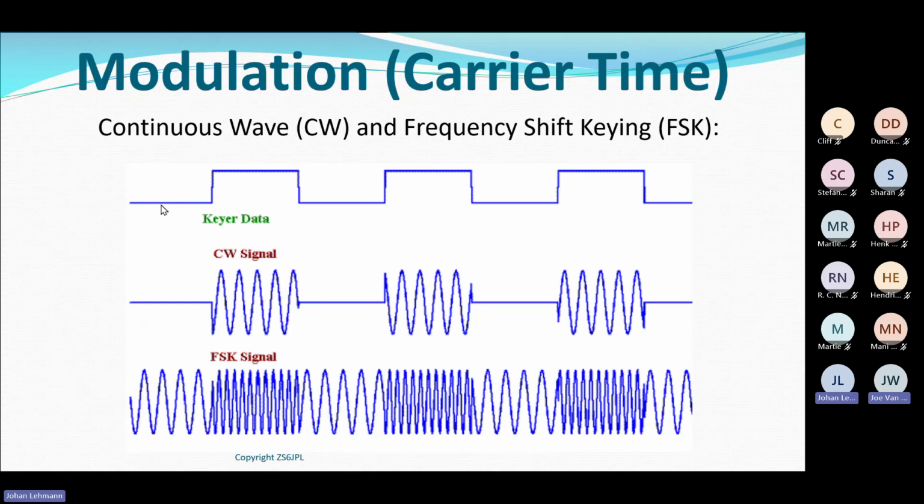So when my signal is not true or it's a 0, I oscillate at a certain frequency. Let's just take an example, 1 megahertz. The moment my information that I want to transfer becomes a logic 1 or a true value, I jump to 2 megahertz. And when it goes back to a non-true state, I would then go back to 1 megahertz. So I jump between 1 megahertz, 2 megahertz, 1 megahertz, 2 megahertz as my information changes state.